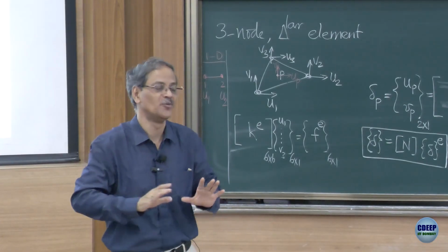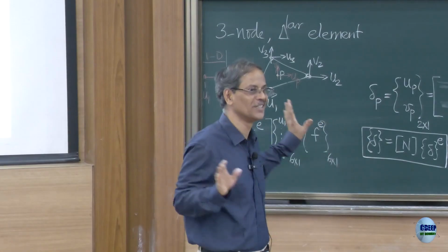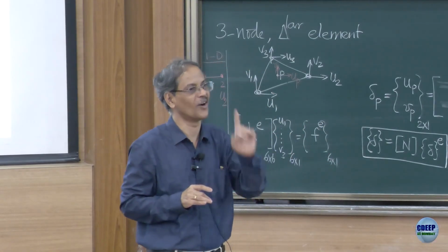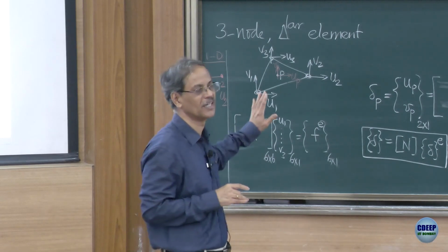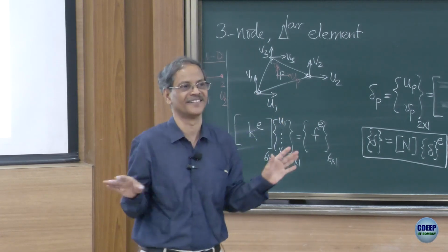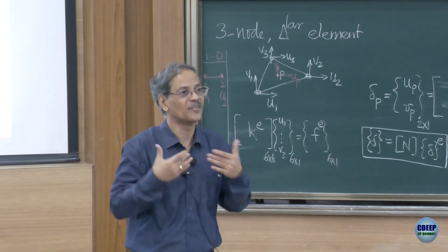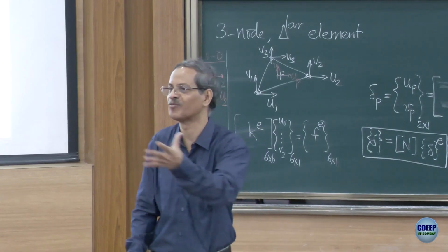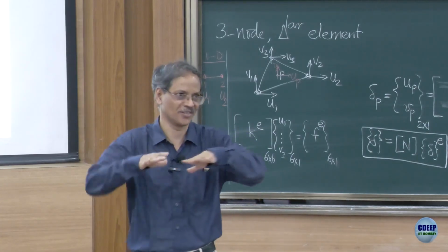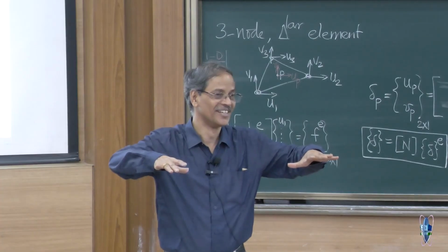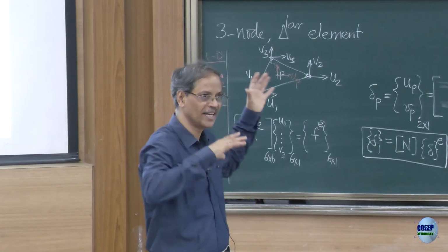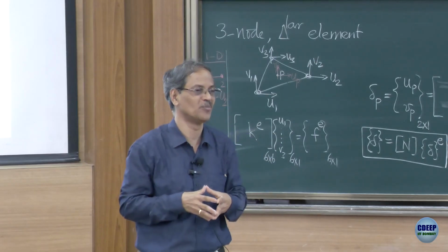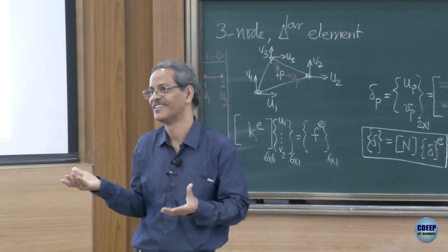You may use a million finite elements based on this derivation, but if in the actual problem the deformations are large, you are not going to get accurate results, period. So, it is important for you to understand your courses on solid mechanics, heat transfer, fluid mechanics, electromagnetics, whatever is the field, how these equations came, what were the assumptions, what is the applicability of these equations before you plunge into finite elements.